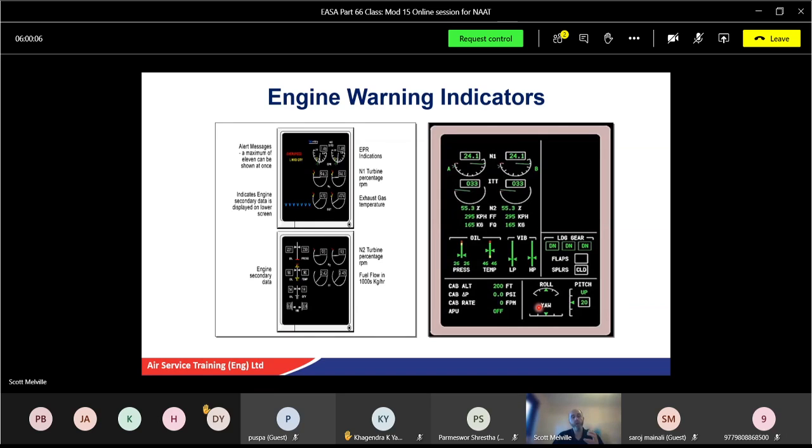So the pressure will move the piston, and there'll be a sensing line off that system to your gauge. That'll provide an indication of torque. Again, it must be carefully monitored by the pilot and indeed the system. If there's too much torque, that can overstress the engine, especially when you've got twin controls going on. If it's a single control, then you can usually work that okay. And the likes of manifold pressure for a piston engine must be very carefully considered.